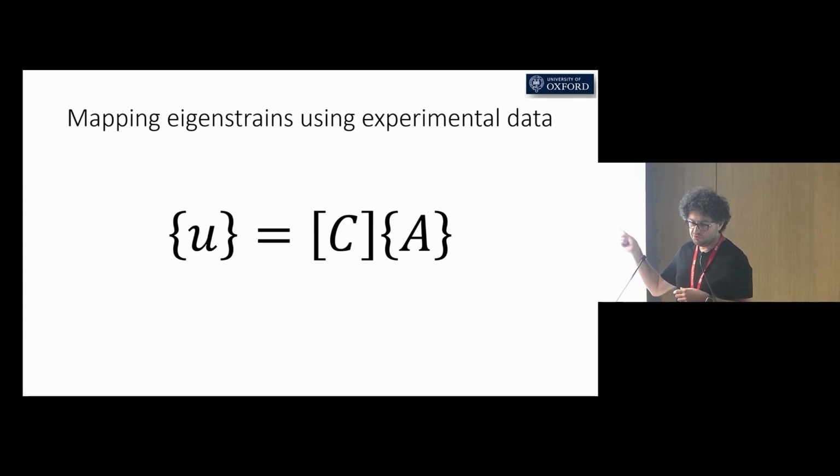And the A vector accommodates unknown weights of independent solutions of the basis functions. So the linear solution of this problem gives us the weights of the independent solutions. At the end, based on the principle of superposition, when you sum them up, it gives you the state of stress and strains.